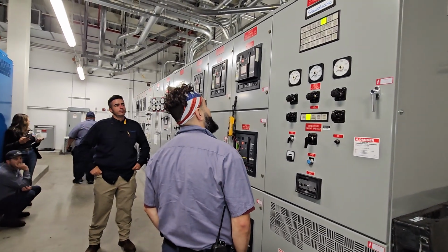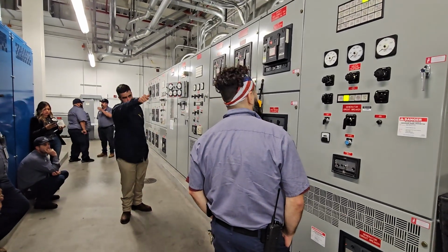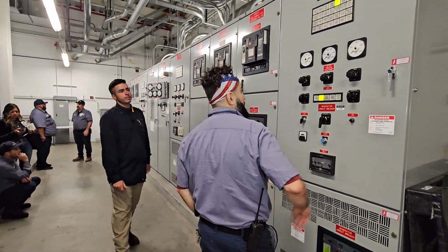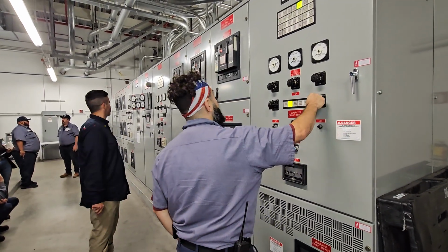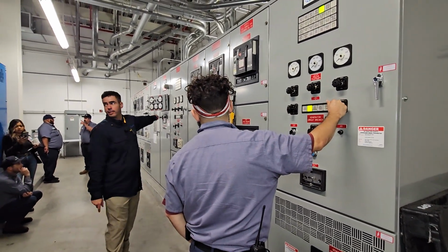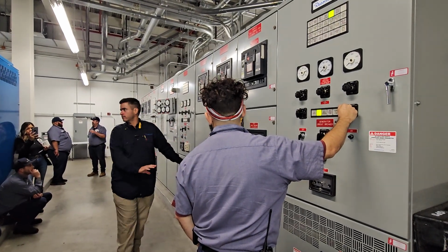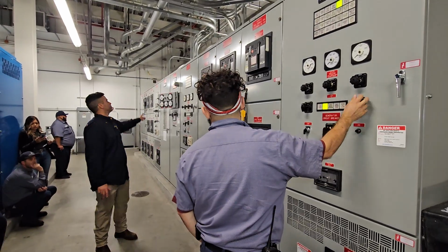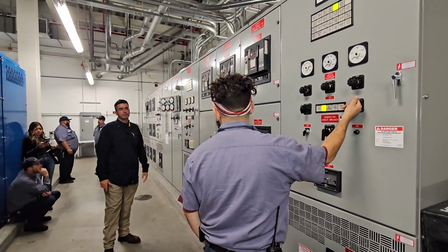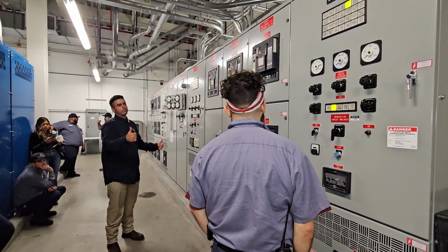480. Yeah. Unfortunately, the frequency meter is not working, but we are gonna assume. Turn the frequency meter key. This one? Yeah. Turn it to bus. So we see what happened. So when he turned it to bus, nothing happened over here because he's looking at the frequency on the bus, but there is nothing connected to the bus. Right. So turn it to gen, and it should show 60. But that thing's busted. Yeah. So we're assuming that we are on 60 hertz. Now we're good to go.